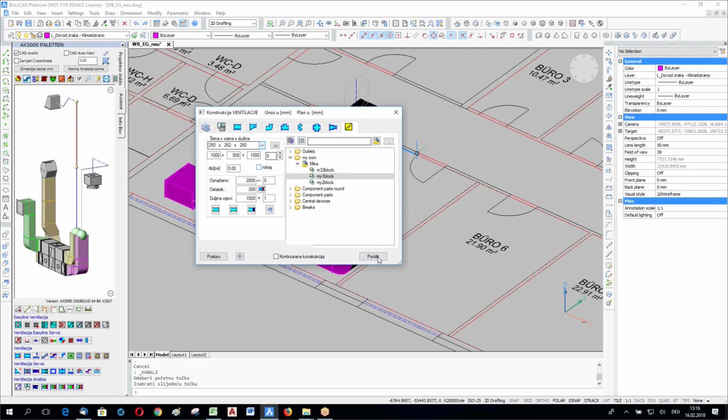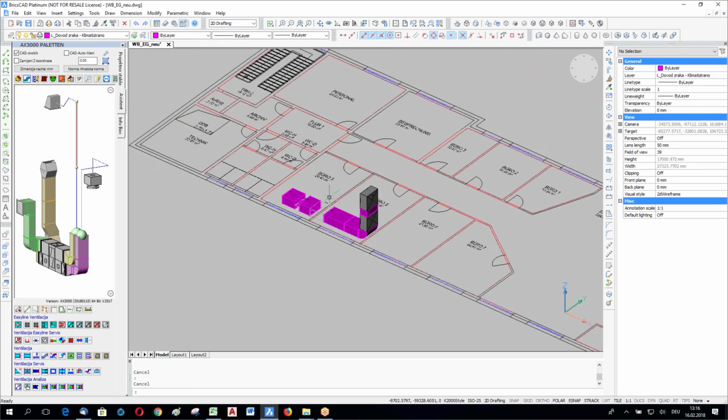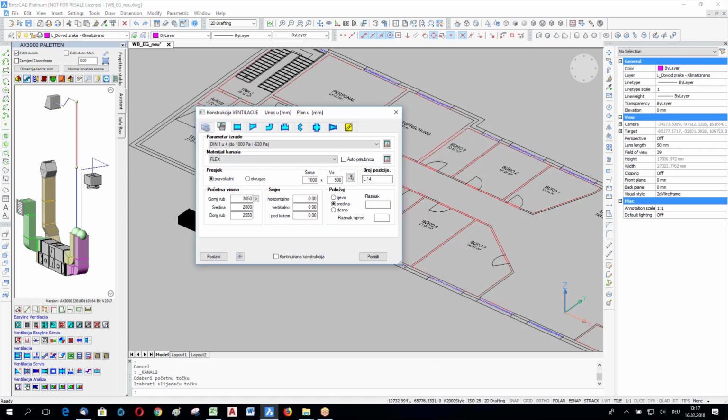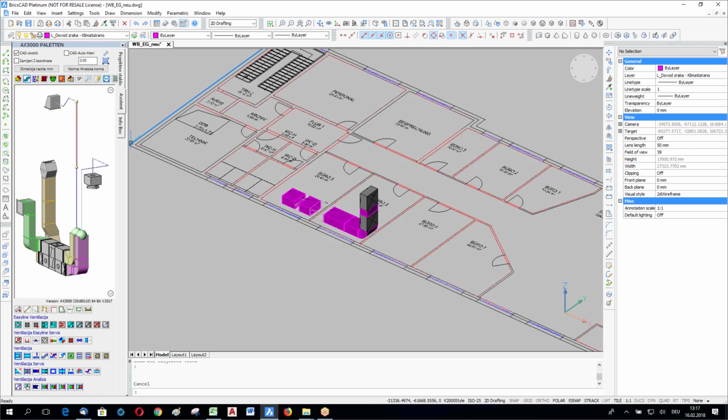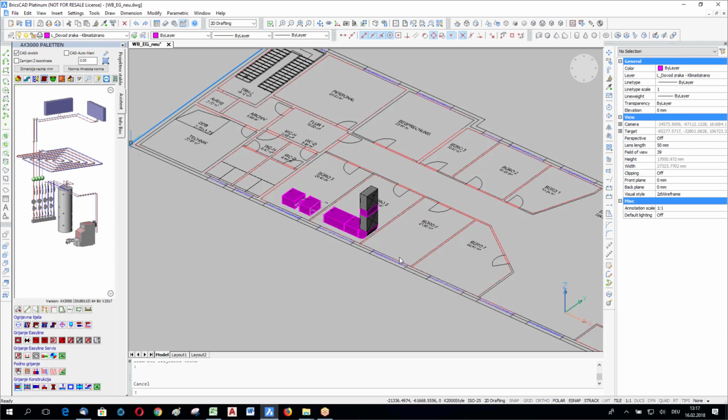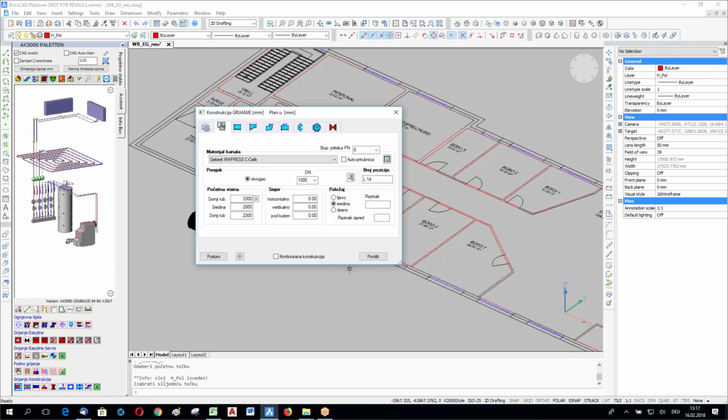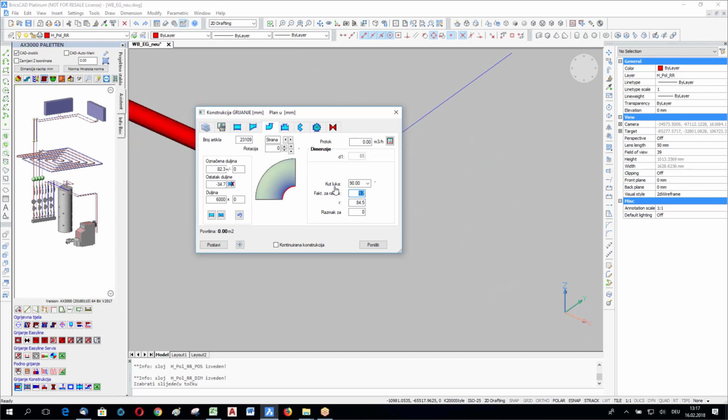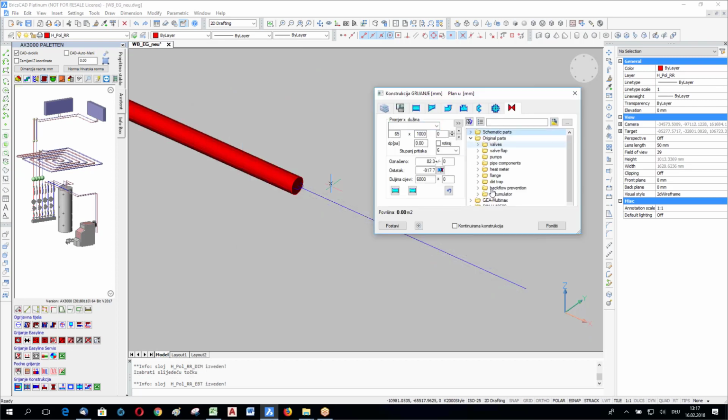This is the first and the easiest block table. If you have blocks, for example, in piping, valves, pumps, whatever, let's start with a pipe, whatever, dimension 65. And I ignore the flange. I only place a valve first, maybe a ball valve, whatever, 65. And you want to have it in the original geometry. This block is not in the size 1 by 1 by 1. This block is in original size.